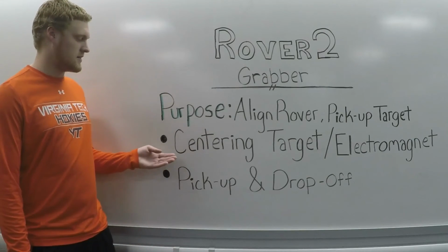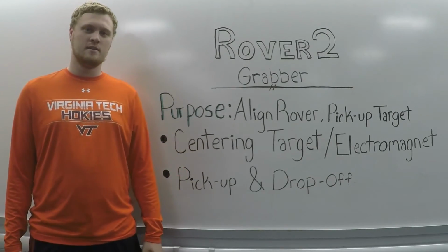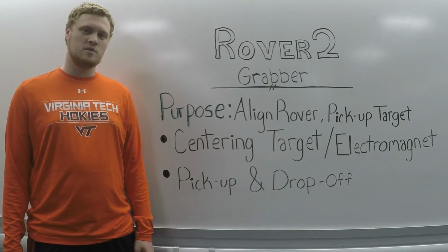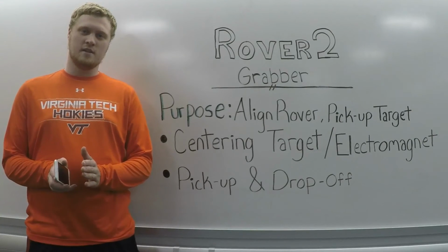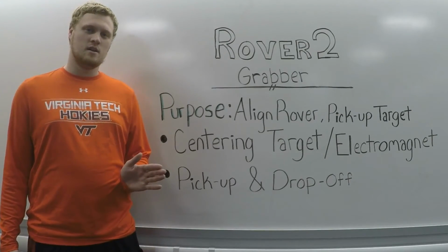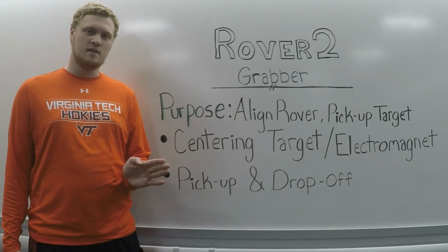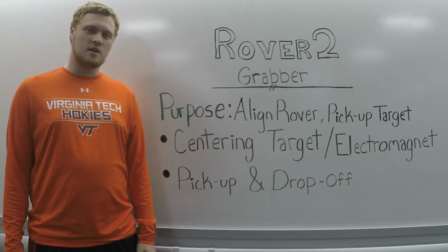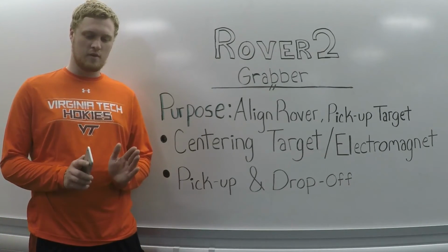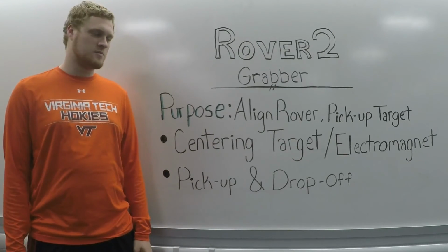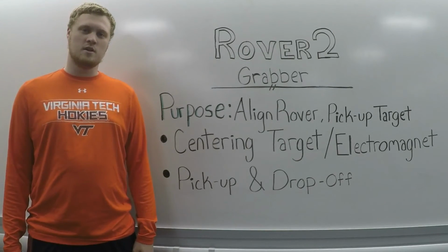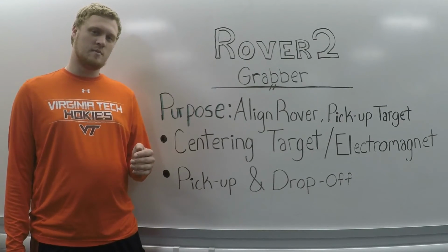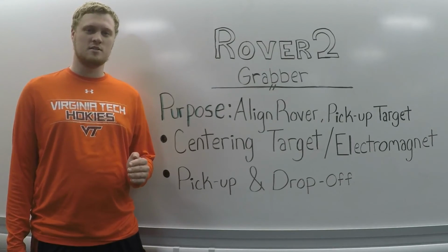The first step of my process was to center the target in the electromagnet. This was done by using an edge detect algorithm using the 3 IRs on the front of the rover. Josh would sweep the rover either right or left, and I would detect the first edge using whatever sensor was on that side, the middle, and then the opposite side. I would then send magic values to Josh telling him to stop and center the rover at that coordinate. The next process was to get the distance. The distance to the target was found by slowly incrementing the motor towards the target until we reached a magic value again, at which point I told Josh to stop the rover.